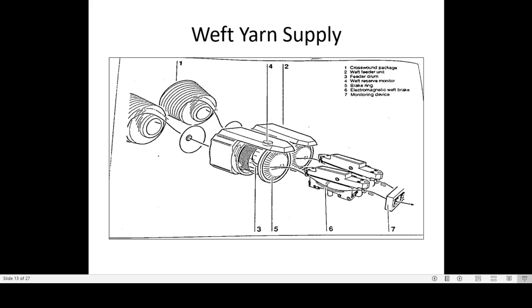So this winder is winding the coils on the drum. The winder stops. After this, the weft is on the brush. Here the brush is there to clean the weft or to control the balloon size in between the accumulator and brake. The brush, or brake ring. What is it called? Brake ring.